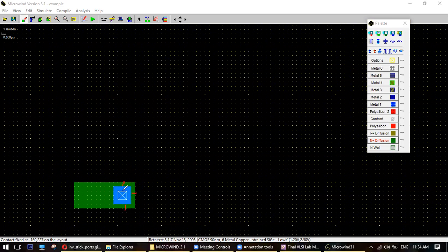It is either drain or source, so you have to design. You have to take one for your source as well. If this is drain, that will be source. Take another N and place it here. In the middle, the gap should be 4. That's why it is 14: 1 gap on the side, 4 in the middle, 1 gap on the other side, plus the contacts. Got my point?